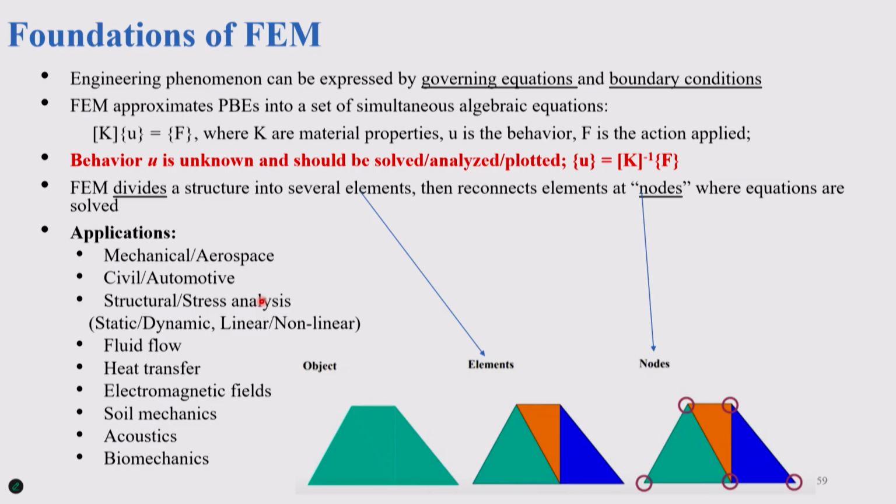So, the foundation of the finite element method. Once you have the boundary conditions and you can represent a partial differential equation like the Poisson equation or heat equation in the form of K u equals F, where K is the material property, u is the behavior like stress, strain and so on, and F is the action applied, then you can simply do u equals K inverse F. Matrix inversion, remember linear algebra?